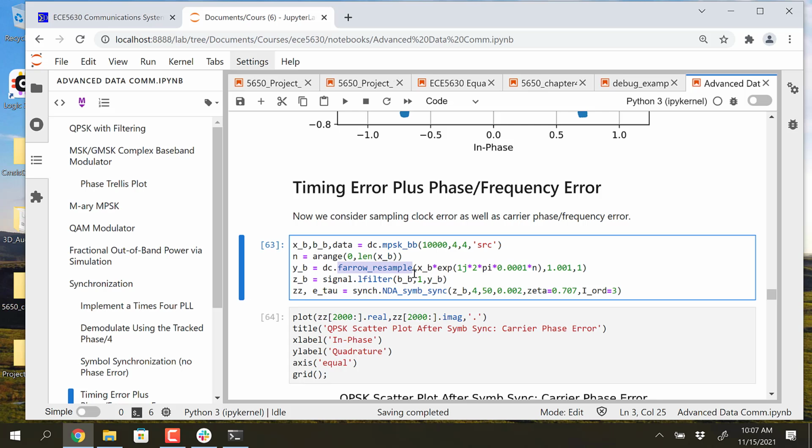So when I worked there is when I created the need. I was doing it in MATLAB, but that is when I needed to do this. And then I had to create a means to screw up a signal because I needed to have test vectors that could test the robustness under clock errors. And in that work, they told me what the parts per million of the crystal clock oscillators were that were part of this IEEE standard, 802.15.4, and it has embedded in that standard what is the ppm on the clock oscillators, parts per million accuracy. So I had to be able to pull in and track a signal that had so many parts per million.